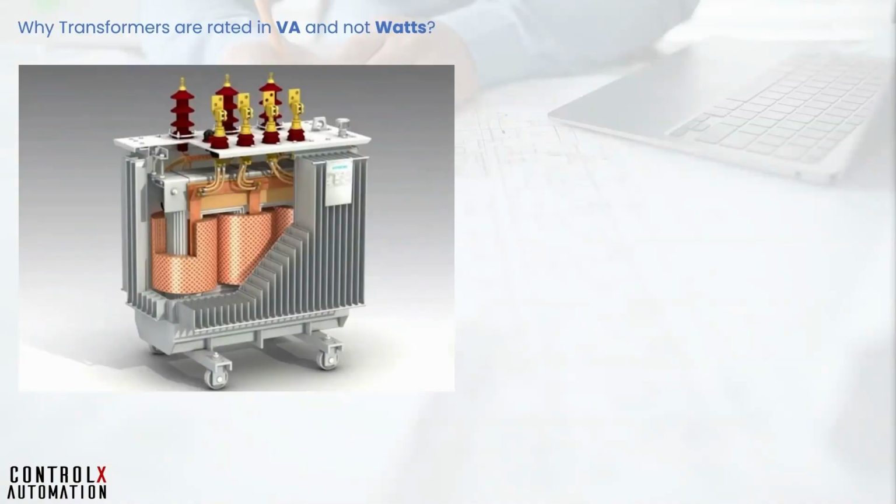To grasp this concept, we must first understand the three types of AC power. In any AC circuit with reactive elements like inductors and capacitors, power takes three distinct forms. First is the real power, P, with units of watts. This is the power actually consumed and converted to work or heat by the load. It is used to turn a motor, heat an element or a light bulb. Resistive loads like heaters and incandescent lamps consume only real power.